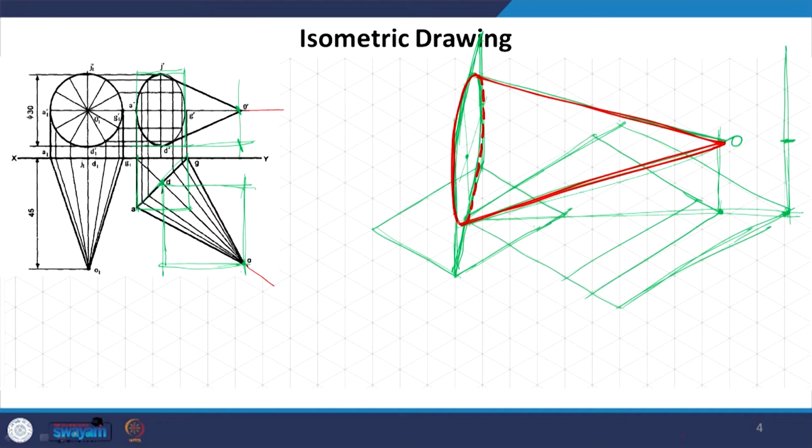So, now you can see that there is a cone which has its base perpendicular. I am talking about the base, not the axis. Okay, I can also draw this axis here. But what you can see here is that there is this base which is contained in this reference rectangle, which is perpendicular to HP, and it is inclined to VP by a certain angle. And I repeat it all the time, the angular lines which are not parallel to the axis in isometric projections cannot be drawn. The angle cannot be ascertained. It is not possible. Rather, we should not try doing it.